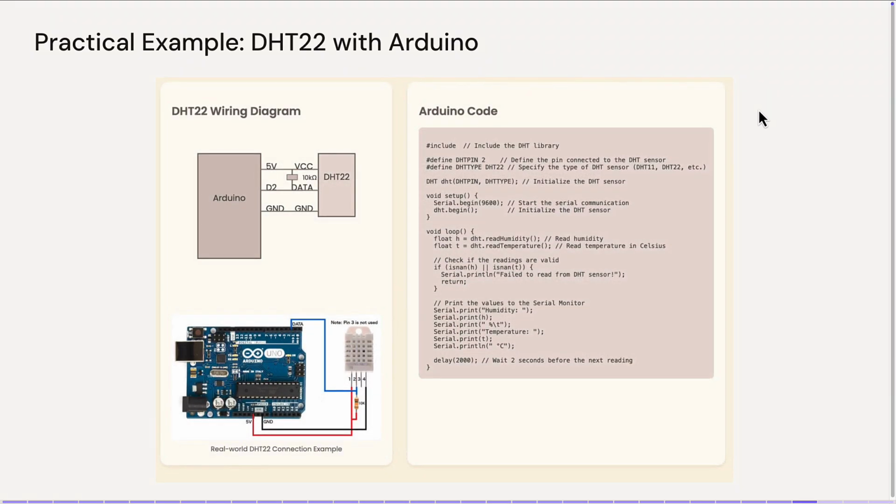And this is how we connect it. Okay, you have an Arduino board. You have a sensor. It can be the DHT22 or 11. This one comes directly with a simple connection. Based on the pins, you will have a pin that connects to the 5 volts, another one to the ground, just to provide power to the sensor, because the sensor has to be powered with 5 volts. And then you have a data link to collect the data from this one. Okay, and this is another diagram. So here, for example, port 2 is for the data link, and here we connect it to the 5 volts, and here we connect it to the GND.